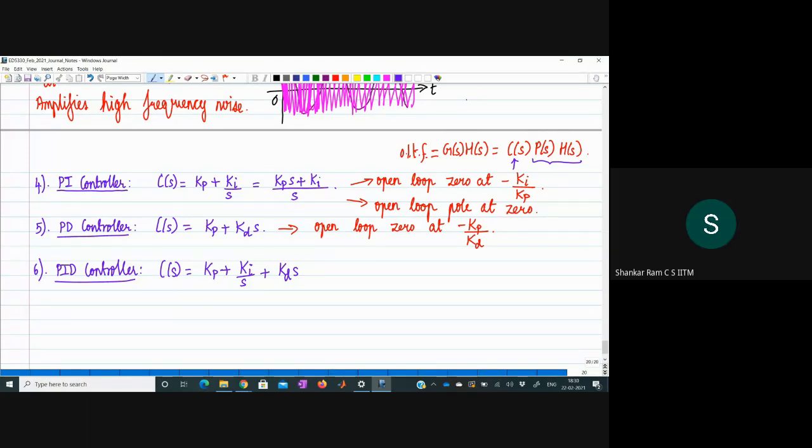That is the definition of the transfer function. If you look at any transfer function, it's a ratio of two polynomials in s, right? The numerator order is M, the denominator order is N. So for a proper transfer function, we need M to be less than or equal to N. So please don't correlate non-proper or improper transfer function with a negative connotation. That's not the intention. That's the terminology. It's just the jargon which is used.